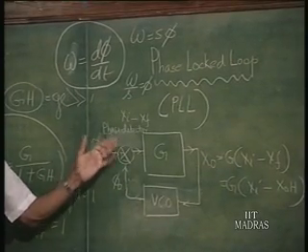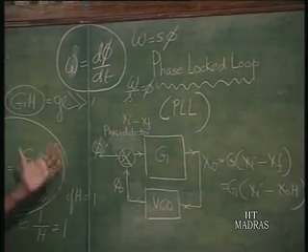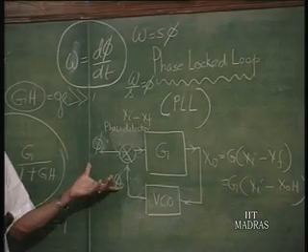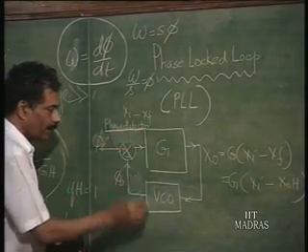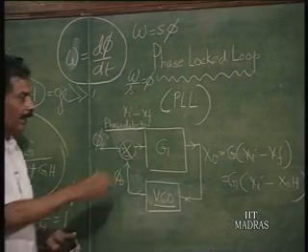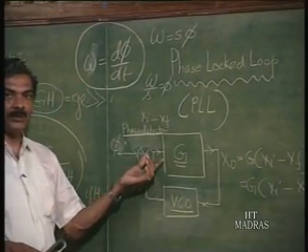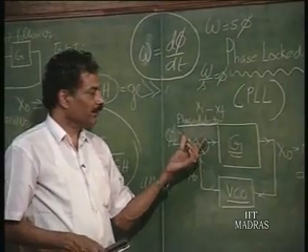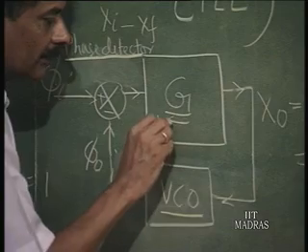So, if the frequency output is given to a phase detector, it will respond to phase change. And therefore, the basic building blocks of a phase lock loop will be a phase detector, a VCO, and an amplifier, and it should respond to only the average here because I said DC. So, an amplifier with a low pass filter.